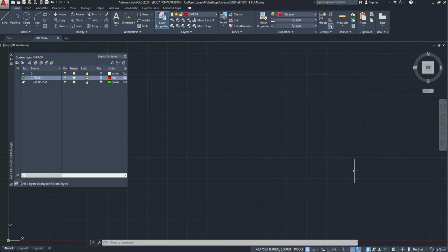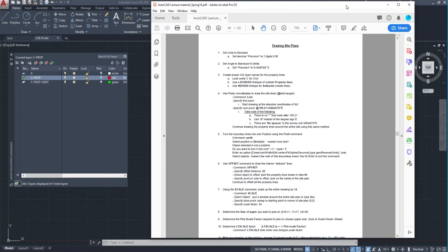So what that means in terms of using an architect using a site plan, an architect has to take a site plan that is drawn by a civil engineer and scale it up by a factor of 12 to convert it from decimal inches to feet and inches, okay? So we're going to draw our site plan in surveyor units, and then we're going to scale it up by a factor of 12 so I can show you how an architect makes it useful for them.